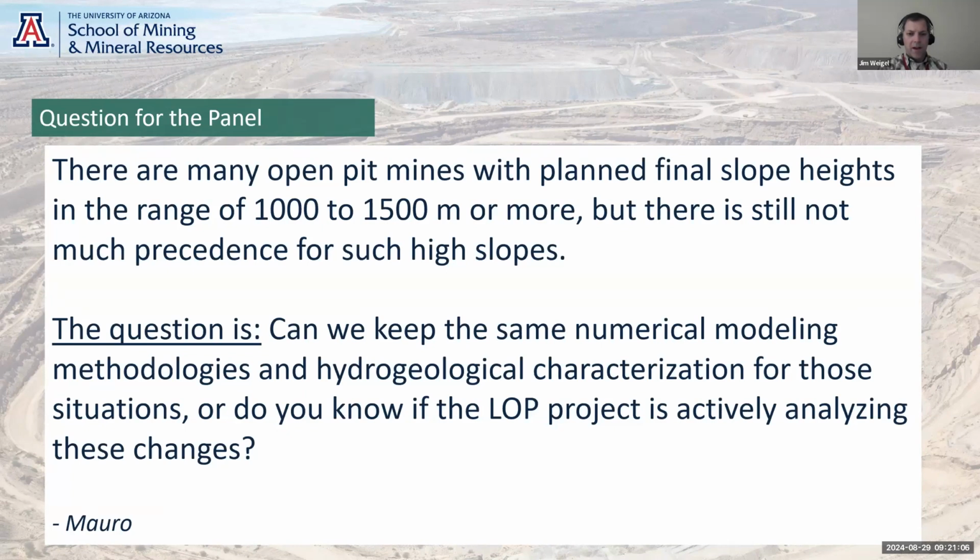But you have to have periodic wide catch benches where you can maintain permanent access so you can continue your monitoring. Otherwise, you kind of go blind a little bit. So that was a big learning as we developed from slice 1 to putting in slice 2, as we're leaving behind these 75-foot to 100-foot wide benches where we can put instrumentation, both hydrogeologic and downhole geotechnical instrumentation. It's really been kind of a game changer.